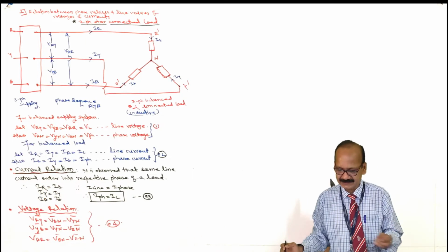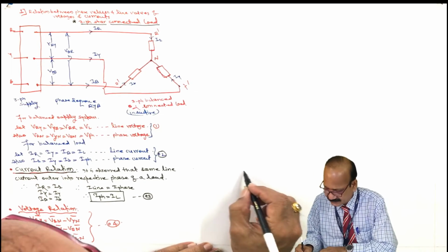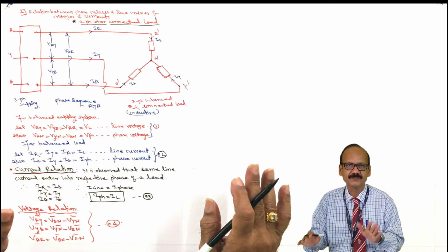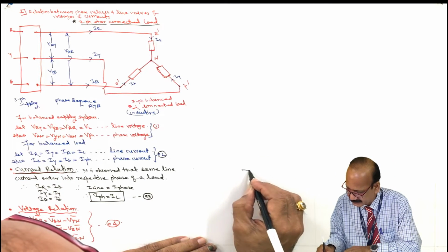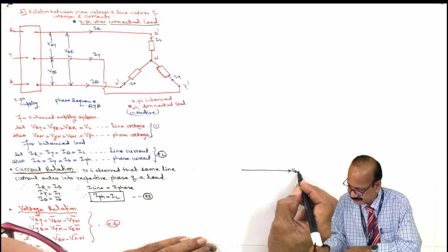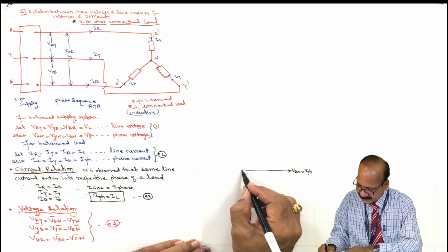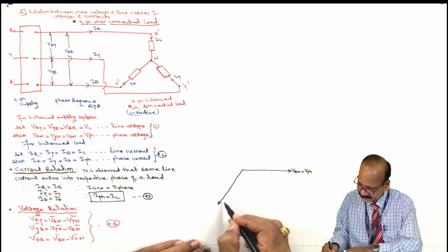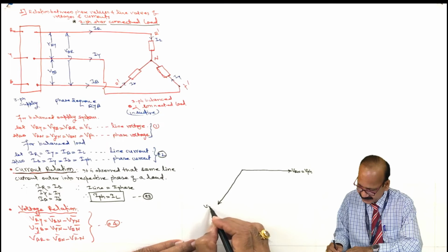Say, assuming that the load is inductive, already we have mentioned. Here we have to draw the phasor diagram on per-phase basis. So first of all, draw VRN equal to VPH. VRN, then equal magnitude. Consider the equal magnitude. Say this is VYN.